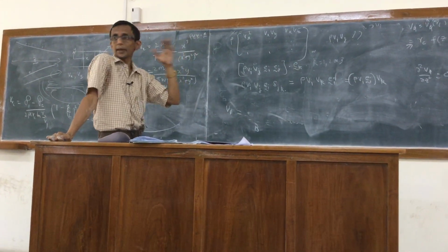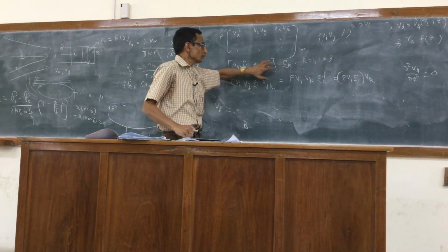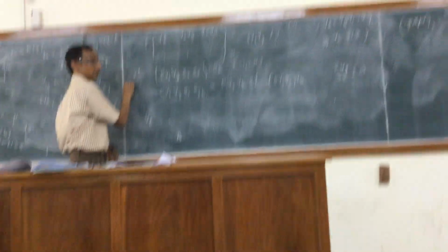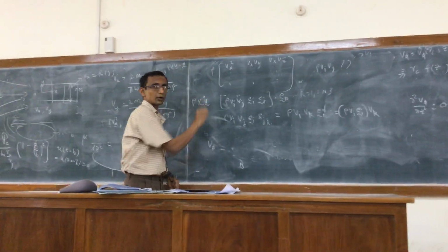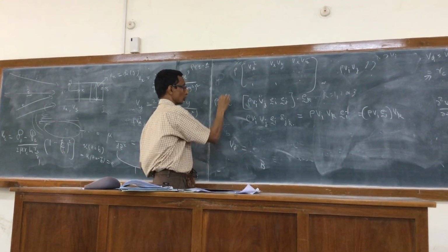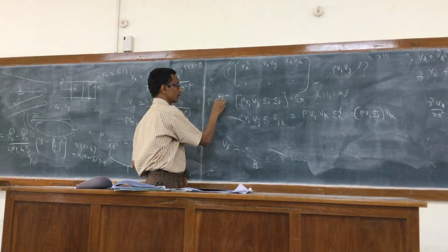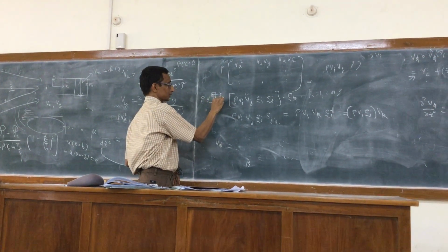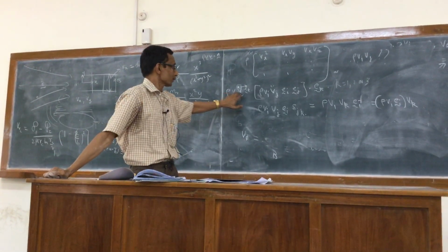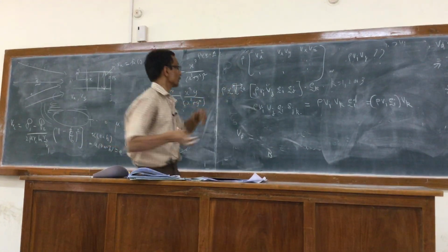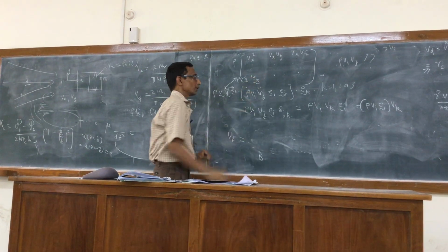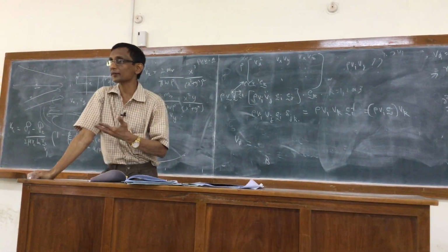What we can regard is that at a point I can define B. I know what rho is, so I can calculate what rho BB is. Now suppose I consider an area element whose outward normal is in the Ek direction. Now this tensor is going to give a vector. So what I am calculating is rho BB dot Ek, that has to give a vector finally. That's the momentum flux vector.